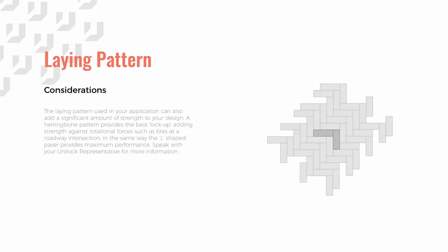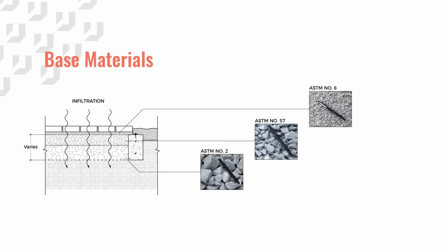When designing a permeable unit paving system, it is important to implement a herringbone or double herringbone pattern for areas that will receive heavy vehicular traffic. Other specialized pavers such as Eco-Optilock and Bronte Street Paver are also acceptable due to their specific lockup features, but when in doubt, consult your local territory manager.